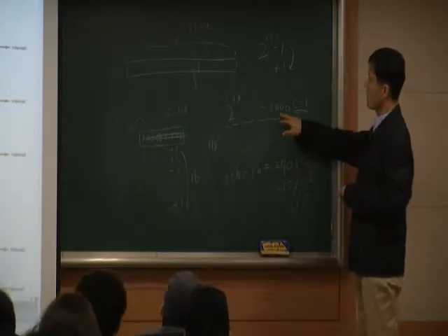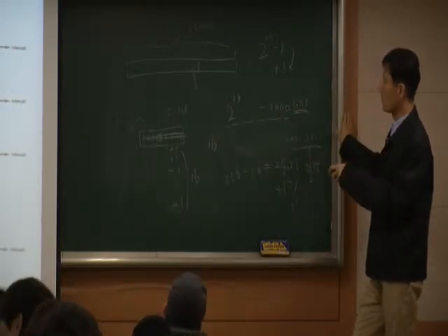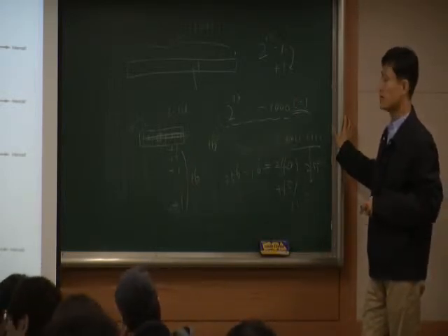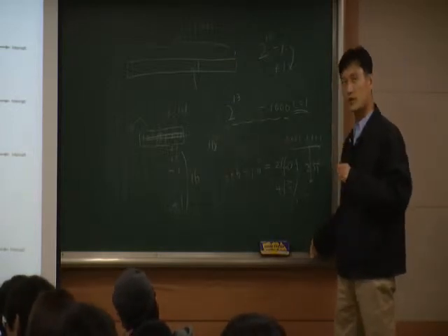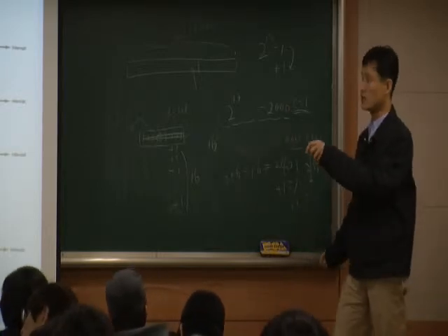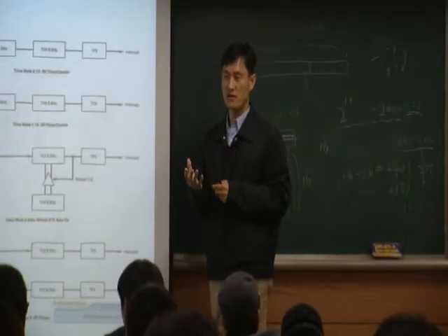This probably is the initial value you want to write here. That way, when you have 1,000 pulses coming in, now you have a carry, and all the bits remaining in the counter become 0. Yeah, right. So this is the initial value you want to write. And if you want to count 2,000 pulses, then simply this is going to be the initial value in your program, in your counter. That's how you run the timer.